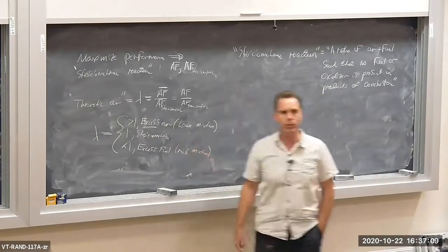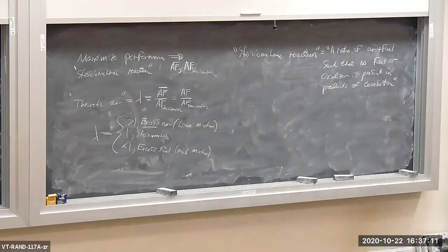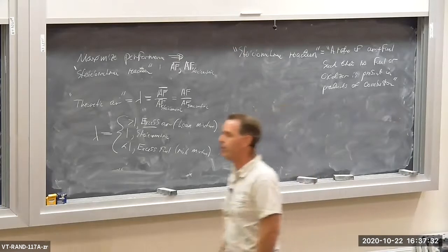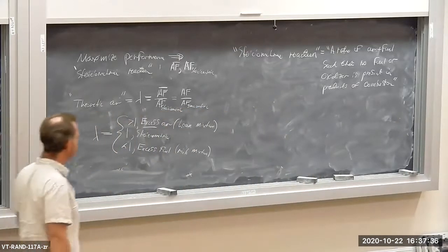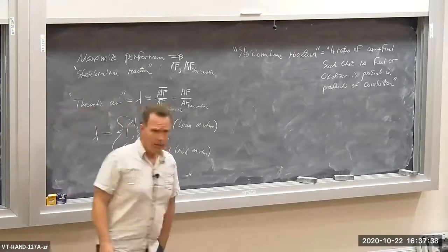So today, with catalytic converters and electronic fuel injection, the idea is to approach as much as possible just plain old stoichiometric combustion. Not too much, not too little. Some manufacturers are still working with lean combustion, but most of them are stoichiometric. There's still some research on lean combustion engines, and they're making some progress, but they're not there yet. So that's some of the history on theoretical air and the values that it takes: lean, rich, and stoichiometric combustion, okay? Let's do an example.